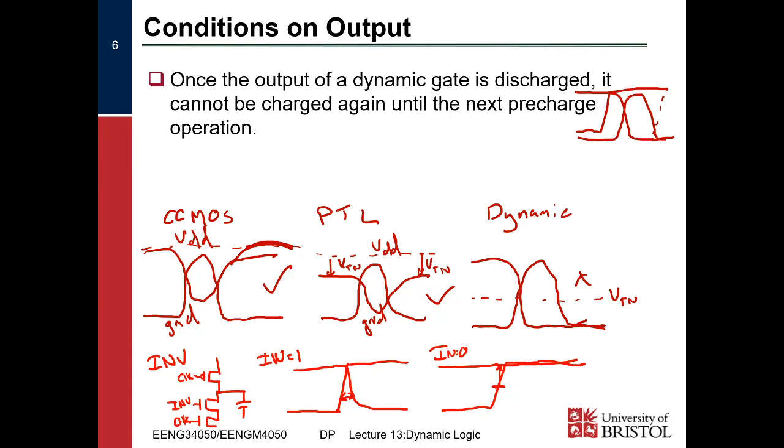I mean, exactly instant. And so this is the key point with the timing of the dynamic logic, right? Because the output is already charged, the time from the 50% point of the clock signal to the output being high must be 0, right?